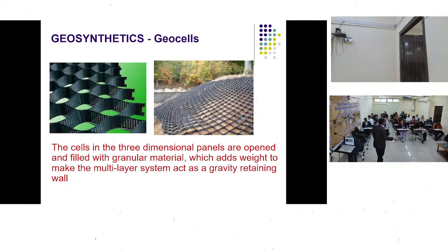And these geocells have been used for various applications. They have been used as foundations in case of weak soils, and also as gravity retaining walls and for making multi-layer systems.